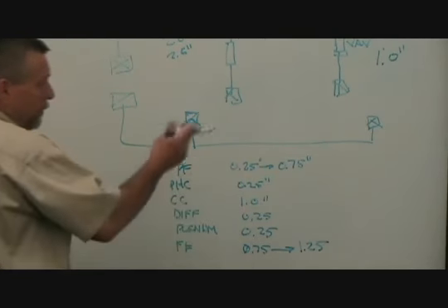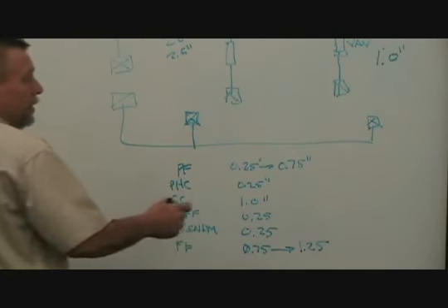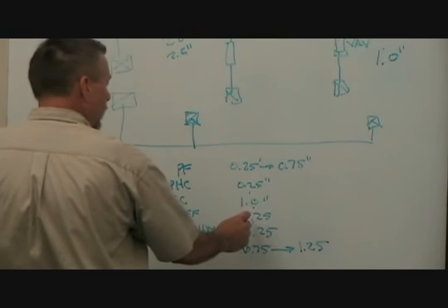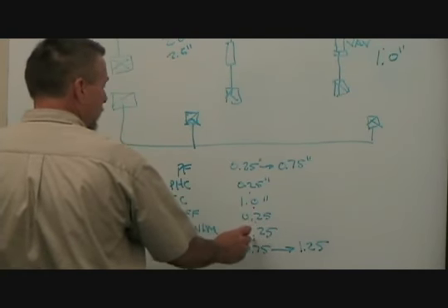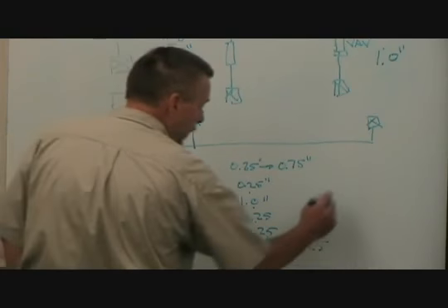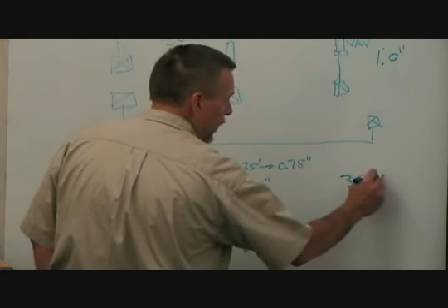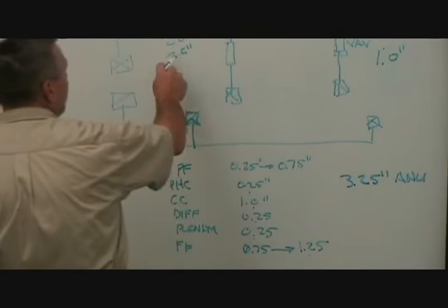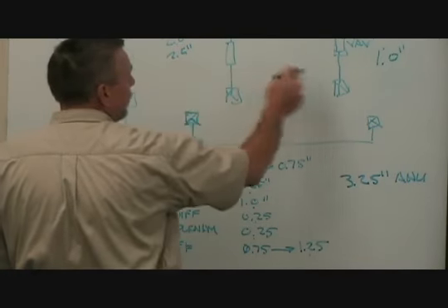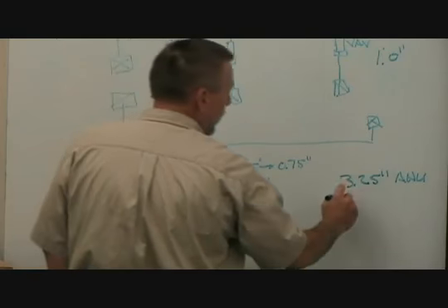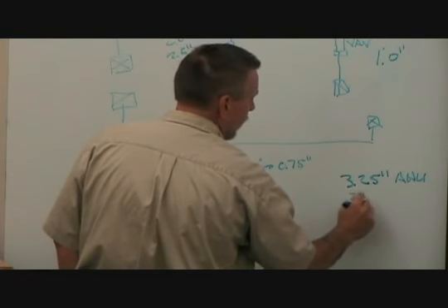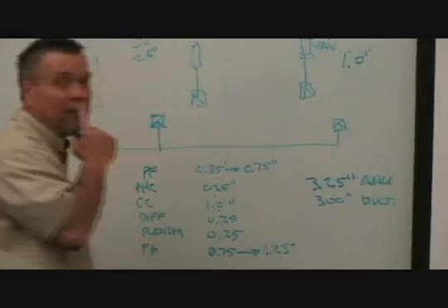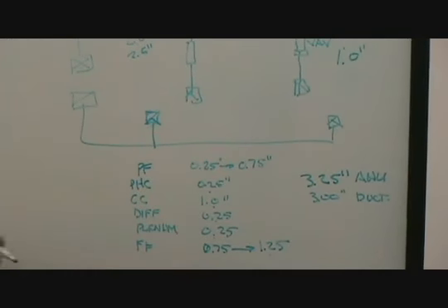So in ratios, like we were talking about between piping and chillers, this adds up to half, 1, 1.5, 1 3/4, 2, 3 1/4 inches for the air handling unit, and 2, 2.5 inches, so probably about 3 inches for the ductwork. And that's pretty typical, pretty typical ratio.